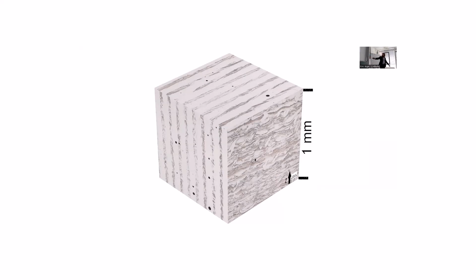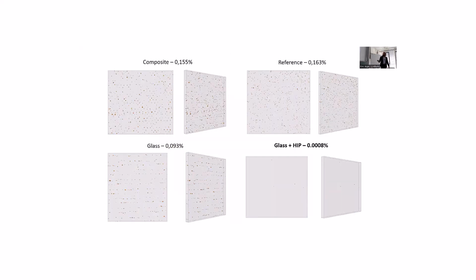The problem, of course, is keyhole melting, and we wanted to have this right from our history. We are using keyhole mode, we are getting pores, the powder is moist, and there is a problem. So, crazy idea: let's hot isostatically press metallic glasses. It's stupid because it will crystallize, but it doesn't. At the end, we found a team in Warsaw with a very particular hot isostatic press that goes up to 1 gigapascal of pressure.